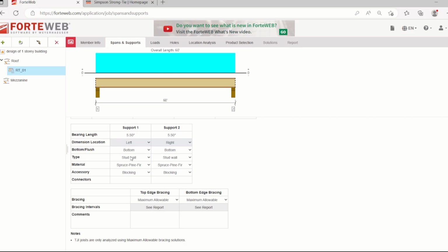So for now, this is supported by studs, then it will be all studs. And then accessories, since this is a roof truss and we don't have rim board, but we have blocking, then you can select blocking. So when you select blocking, it will not subtract from your bearing length. But if you select a rim board, say 1 1/2 rim board, it will show the rim board right here, and then it will subtract from your bearing length.